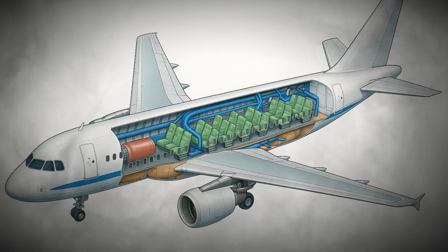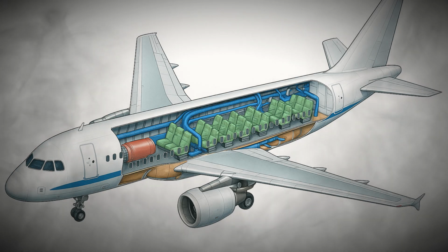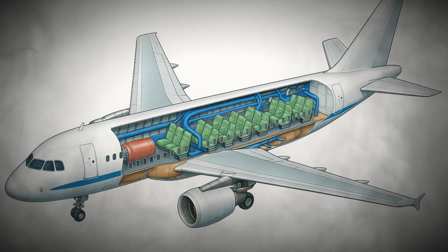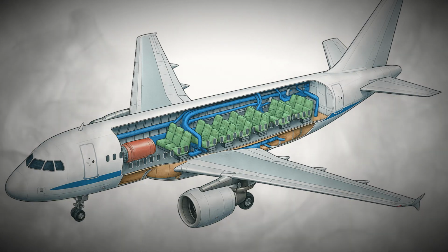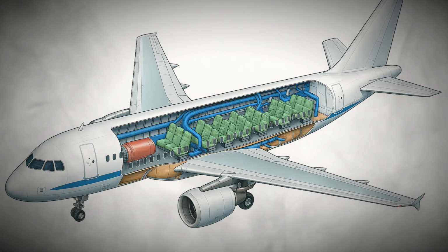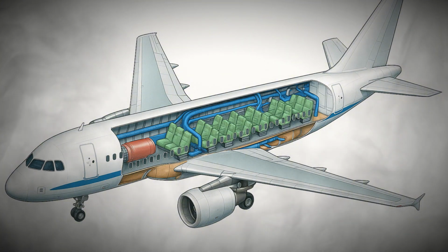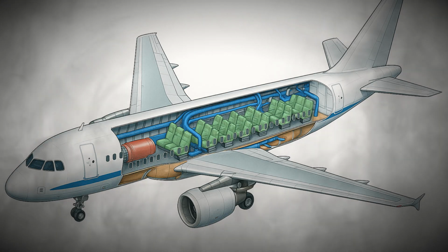If a gust of wind tips one wing downward, the lower wing experiences increased lift due to its steeper angle to the airflow, rolling the airplane back toward level flight. This passive stability reduces pilot workload and contributes to safety.